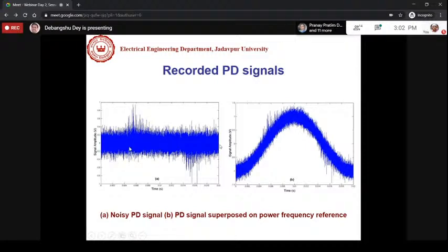But looking at the waveform, you can have an idea that it is very difficult to identify them manually, because there are already certain noises. These pulses generate a voltage of very small amplitude, that can be less than 1 volt, of the order of millivolt. We have to amplify them. I have plotted that in the normalized scale, between 1 and -1. But usually that amplitude is of the order of millivolt in terms of voltage.